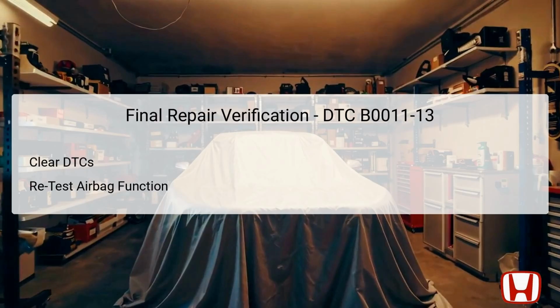After completing necessary repairs, it is crucial to verify that DTC B0011-13 has been effectively resolved. The first step is to clear any stored DTCs using the Honda Diagnostic System, HDS, ensuring a fresh status check. Once cleared, it's essential to retest the airbag system to confirm that it operates as expected without generating the DTC again.